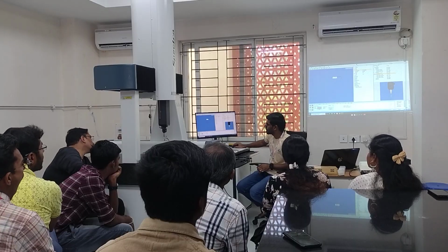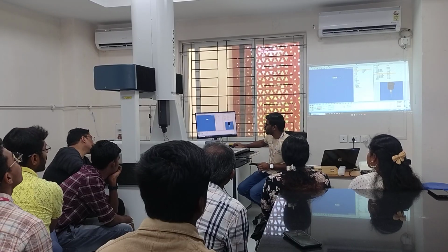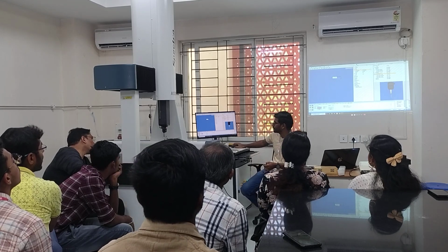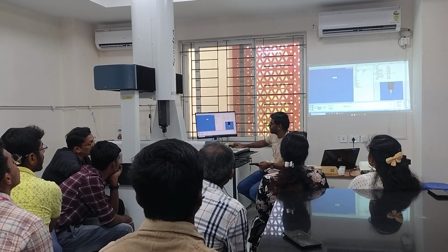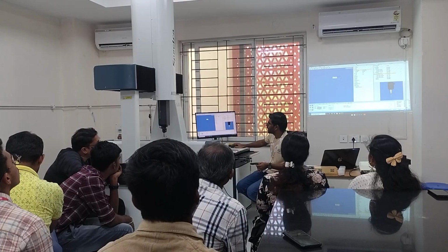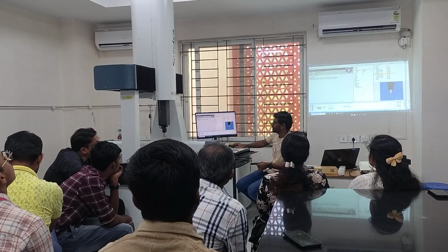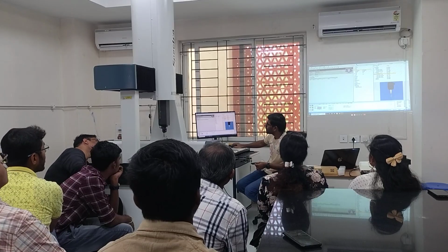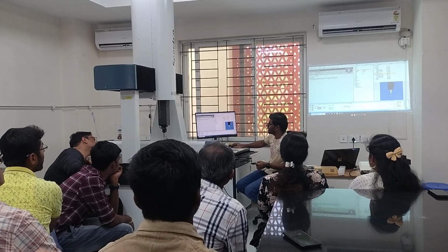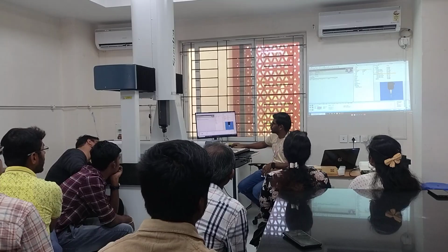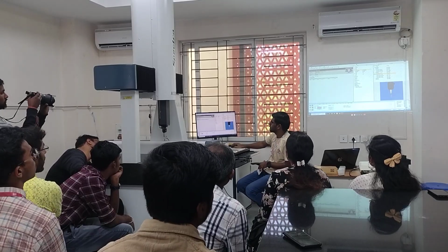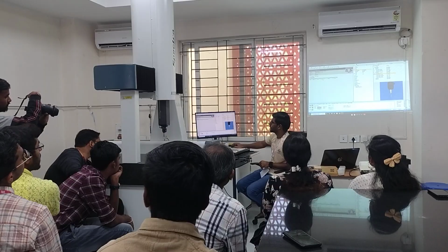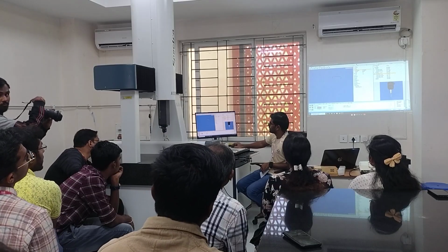So flatness here it comes like 0.01296. So that is the flatness we have got. If I click on accept, it will be showing in our report. So this is how our report is going to come out. So top plane, if it is perfectly flat, it should be 0, and now it is not perfectly flat, therefore the deviation is 0.0130.